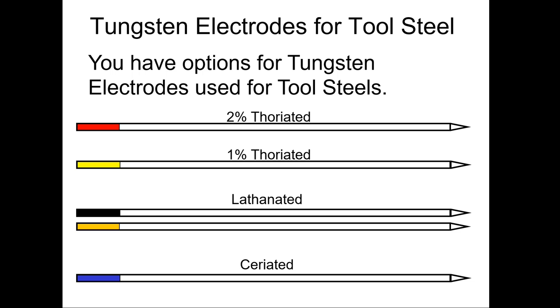So my point will always be, if you guys have a place where you sharpen tungstens, you should have ventilation in that area. You should be taking that ventilation and you should have it ducted in such a way that when we sharpen our tungstens, it sucks the dust away while we're welding.